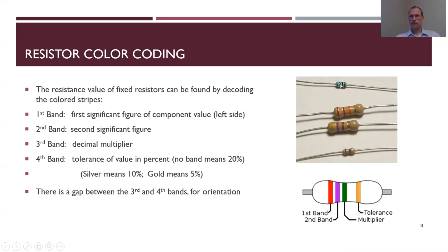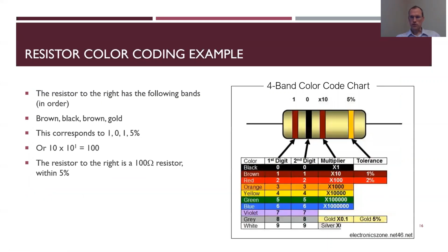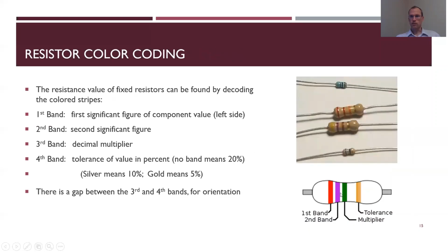The blue ones usually have a different color, whatever 1% is. This will tell me what 1% is. Usually they have a brown one there. So the metal ones usually have a brown as their last value.